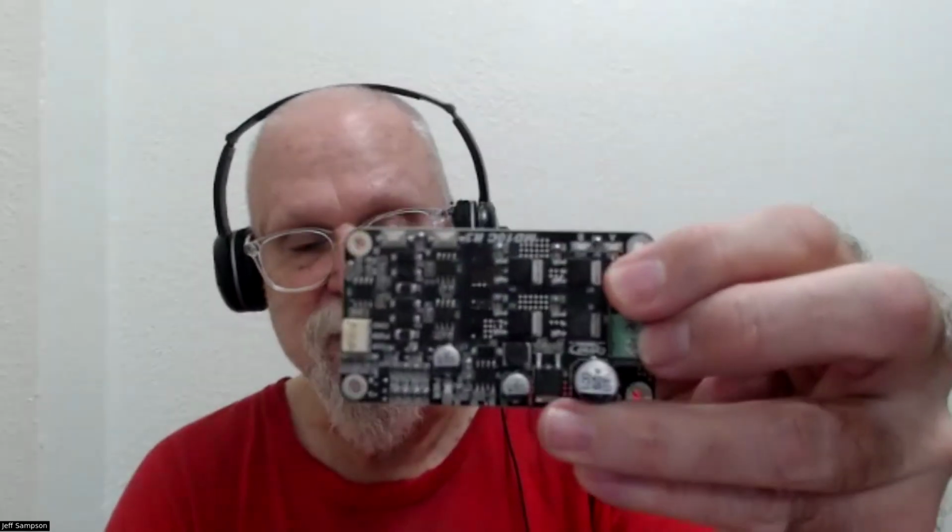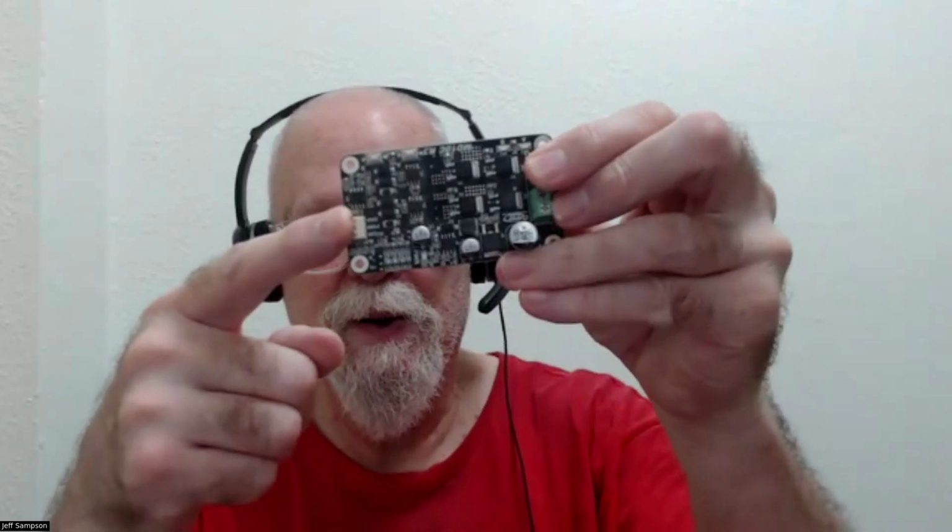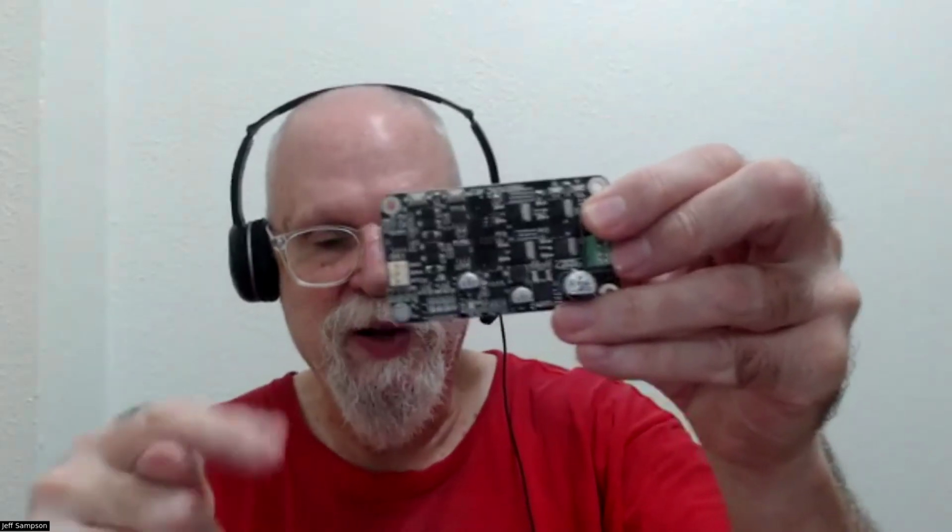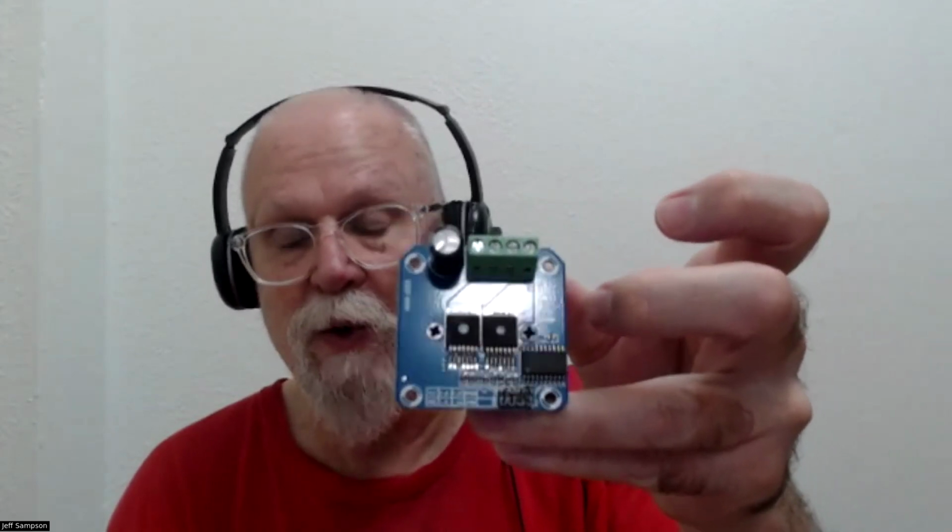And then at one point, when we're talking about the PWM channels, the hardware versus software, if you don't have enough hardware PWM pins, you can create one PWM per board and then create a direction bit. And that's exactly what this board wants anyway. It's got those 3 pins that you feed into it. And then by putting a couple logic gates between that and one of these kinds of boards, you can generate that forward PWM or reverse PWM and make that work. So that's just various things to think about and various ways to get around these things.